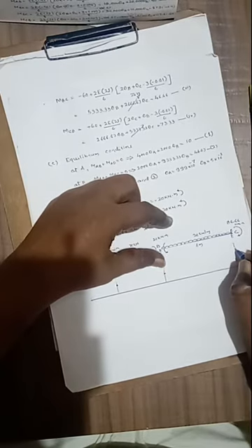Support moments diagram. Here, these are the ordinates. We will consider this one as the reference line. To the reference line, here we have to draw the bending moment diagram like this. By observing these bending moments, all are hogging moments. Here, we will represent the support moments, hogging moments like this. These are the ordinates of the hogging moments at different supports.